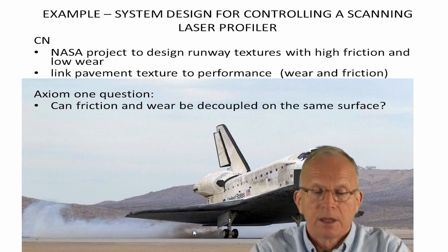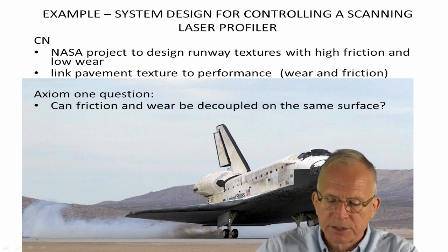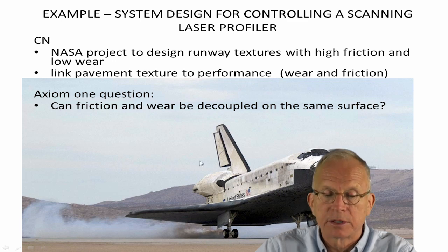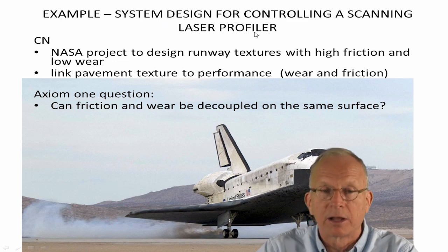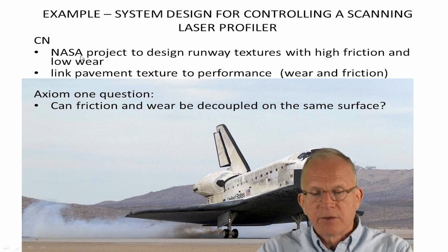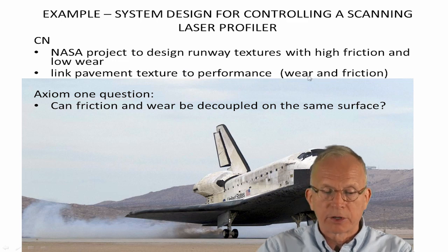All right, so what we needed to do was to study the pavement. So we're looking at this interaction here between the tire and the pavement. And we're looking at a system designed for controlling a scanning laser profiler that will be used to measure the pavement. So they want to see if we could make runway textures that had high friction and low wear, and link the pavement texture to performance, both wear and friction.